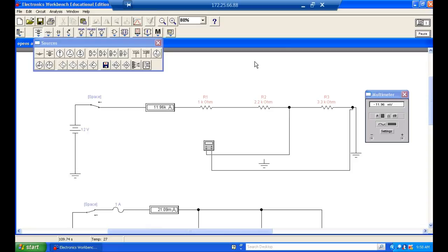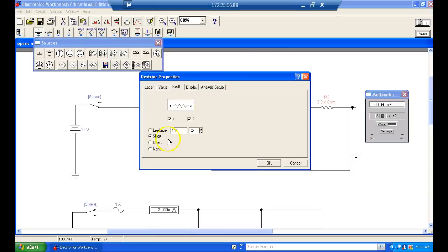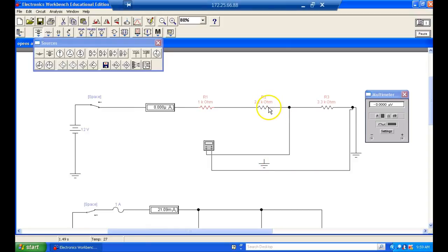Yeah, some of your car batteries have 200 or 300 cranking amps, and that's how much they can put out for a short period of time. So don't take a jumper cable and put it across your car battery. And please honor those polarities on your jumper cable, because if you hook it up one way on one battery and the other way on the other battery, you still got a short circuit, right? So let's open all these, and then we'll go down to the parallel circuit.